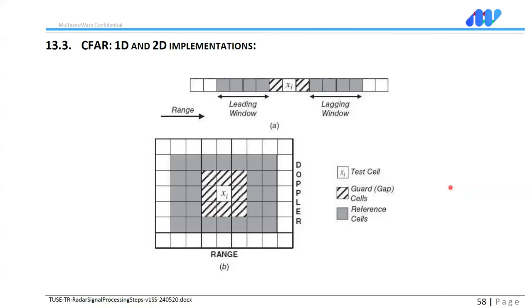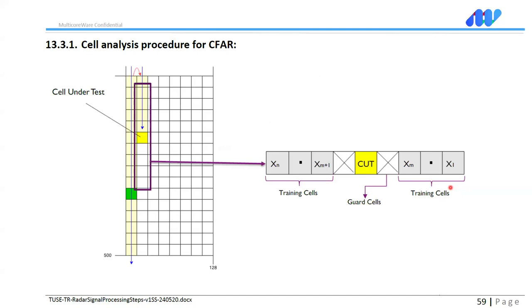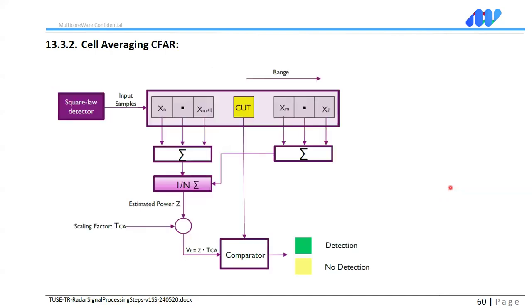And the whole objective is the estimation of the background noise in the vicinity of a target. Basically what you do is you keep the target and the neighboring bins out and simply take the average for a defined window. That's all. And when you talk about average, we mean the average, the median, or the middle element of the order statistics.